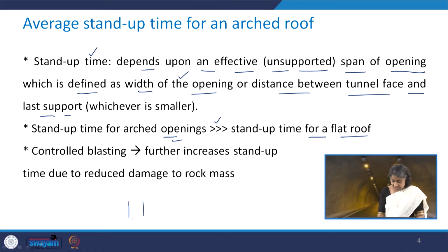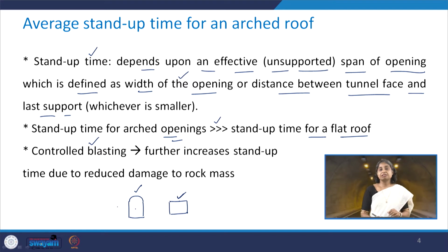One excavation is like this, it has the arched roof, and another excavation is like this, which has the flat roof. So, in this case the stand up time will be much larger as compared to the stand up time in case of a flat roof. If we go for controlled blasting, this further enhances the stand up time, because with controlled blasting we can reduce the damage to the rock mass as compared to random blasting.